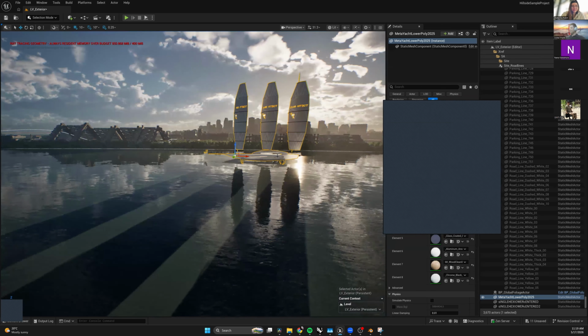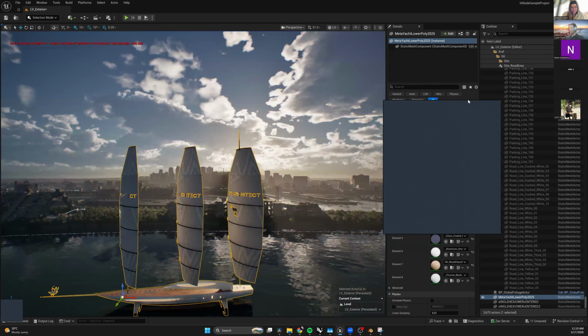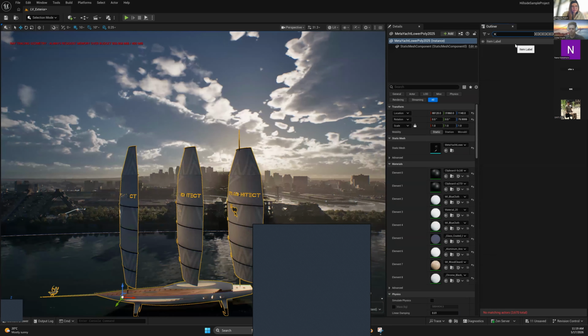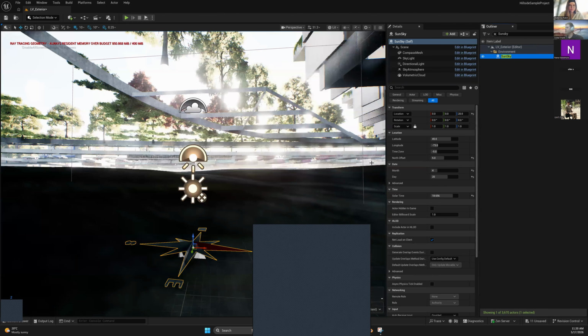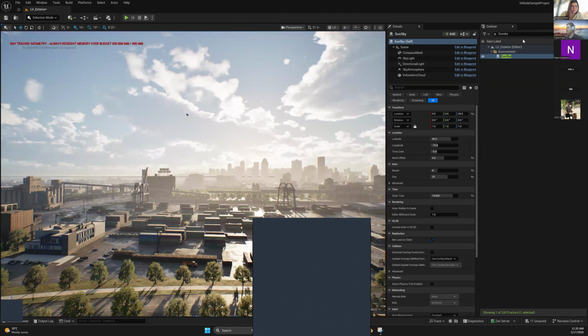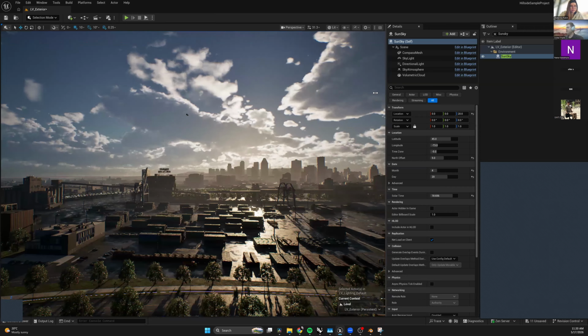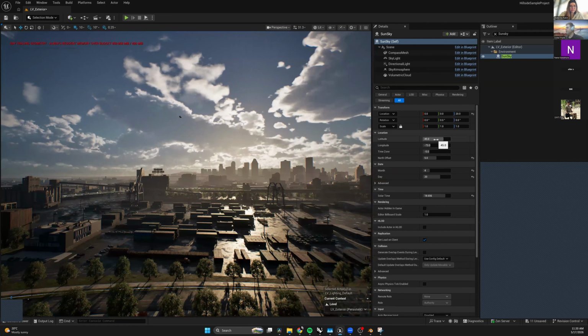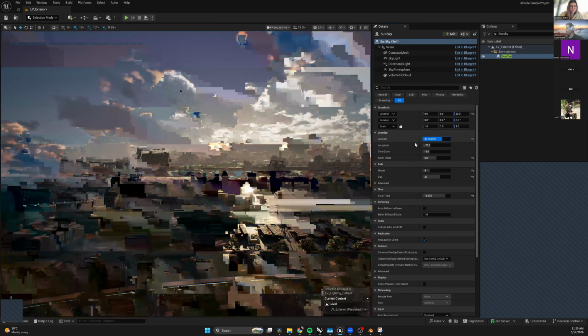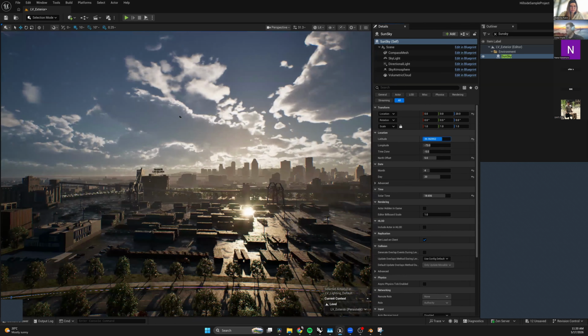All right, let's take this a step farther, right? Let's say you want to set up the scene. We have an ability to control the entire sun, sky and the atmosphere. Sorry, I'm on Hebrew. Let's go to sun sky. Fantastic. So we have the blueprint asset showcasing exactly how to control the sunlight and the amount of clouds. You can see here I have the latitude and the longitude of the sun sky. And if I want to change the direction of the sun or the hour of the day, that's something I can do pretty easily.